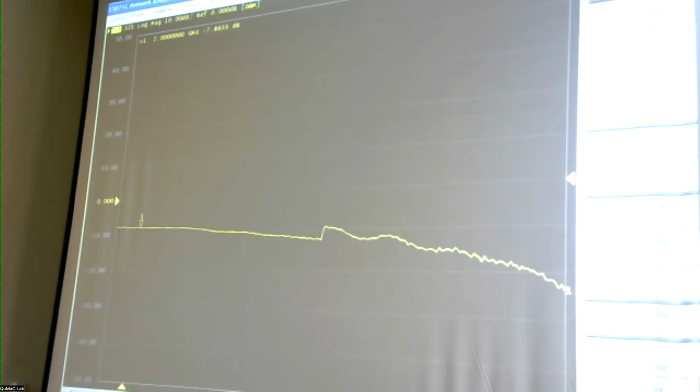So something seriously is wrong, either that the calibration has to be done and hasn't been done in a long time, or there is a serious problem with the receivers. The reason nobody seems to have bothered with this is that for almost 90% of our measurements, we do ratiometric data. So you could be off by a certain factor, but both measurements will be off by the same factor. You take a ratio and you're good to go. So I guess nobody has bothered with this, and I haven't checked it in a long time. That's why the absolute numbers seem to be a little bit off.